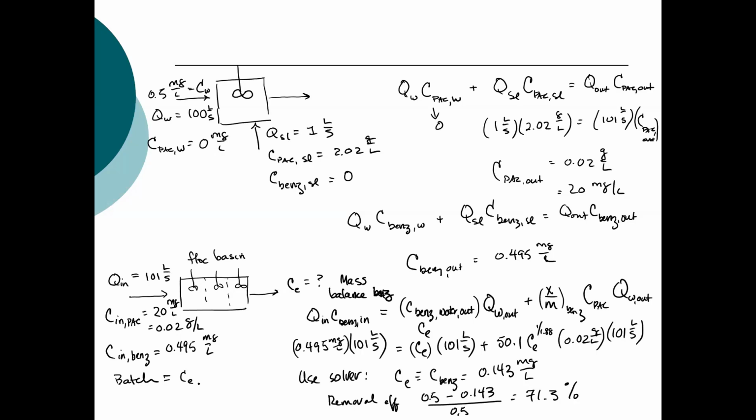How could we make our continuous system more efficient? How might we change this? Can you increase the time that it adsorbs for? Okay, well, we could change the time. We've assumed here that we've reached equilibrium, okay? If we used a plug flow system, so we had a series of reactors, would we increase the removal efficiency? The answer is yes, okay?